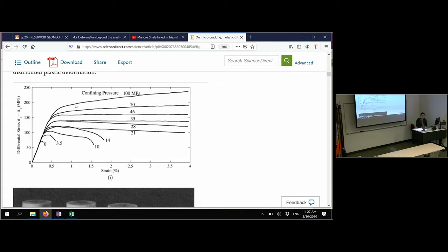And this is very important too, because what these curves are telling you is that here you're going from the surface, a fracture that you may expect on a building made out of marble without any confining pressure, to something that you would expect somewhere over here in the subsurface, where we do have an effective confining stress that makes a rock fail differently than what you would expect on surface.